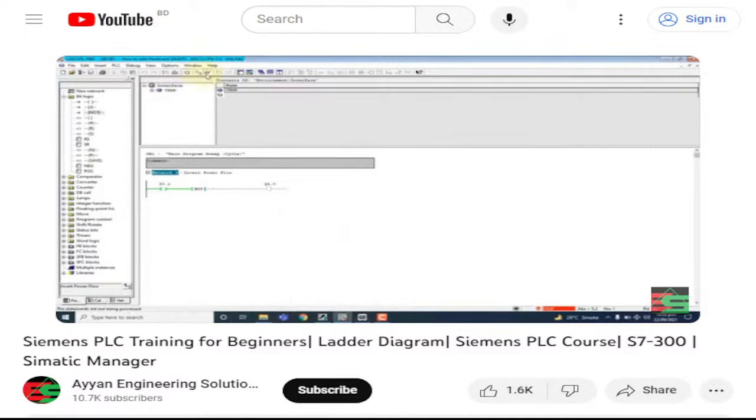And the next one is the coil, which is the same as in other PLC programming, and this one is the midline output. You can see in this rung you can use only one output. You cannot use another output on the same rung. But by using midline output you can use two outputs in one rung. Let's start. We will insert the midline output.